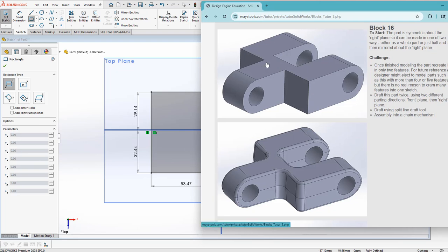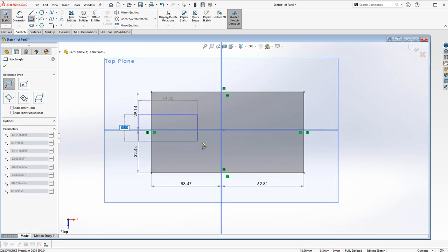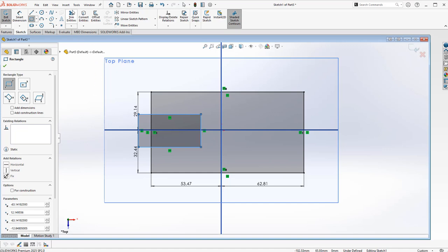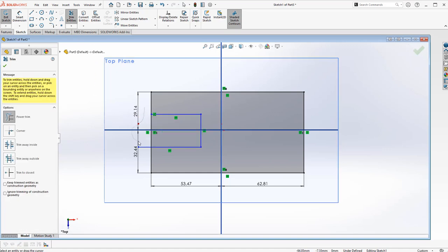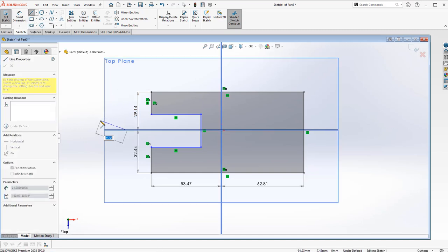So I'm going to build this shape here. I'll build this to the left and the Y shape. So in SolidWorks, I'll just establish that geometry and use my power trim to kind of bite out the portions that are unnecessary. If you do make a mistake, you can cross back over that red dot to undo your mistake there. So I need to establish symmetry, so I'll go ahead and drop down a center line.